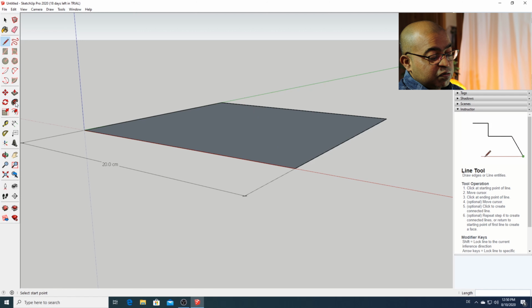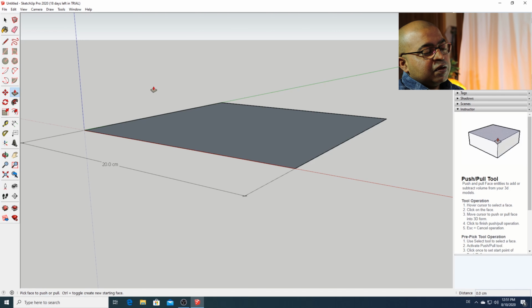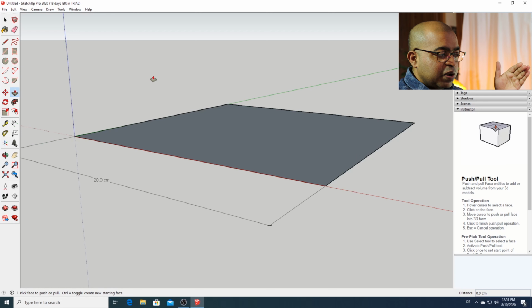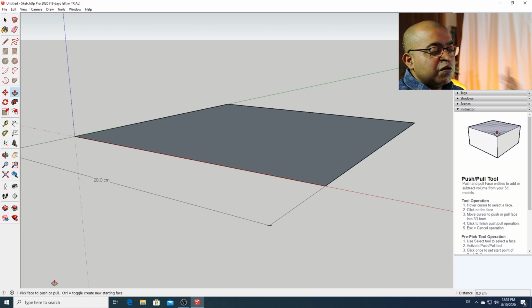Here there is a tooltip, so as beginners that's also very good for us. So I clicked P. Another thing you should remember is the shape of the cursor. With every tool that you select, the shape of the cursor changes. So that's a way in which SketchUp tells the user what's happening. You should also see the bottom right hand corner where my cursor is right now. It also tells you, especially when you are in the midst of using a tool, what happens next.